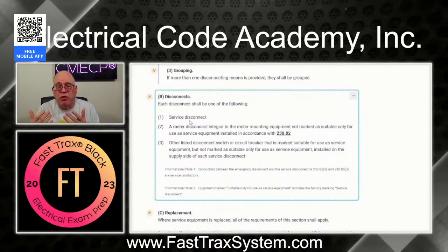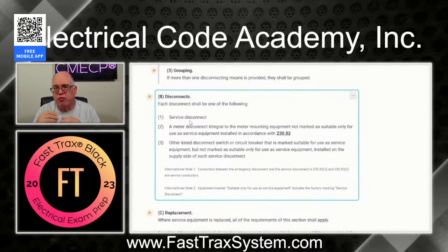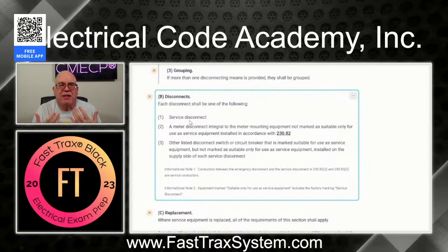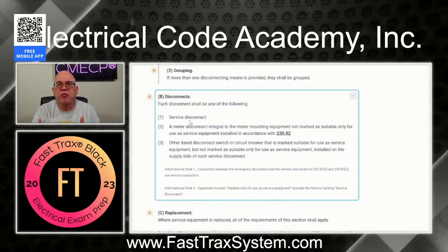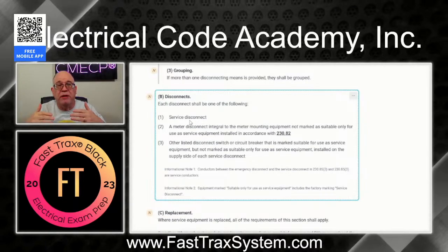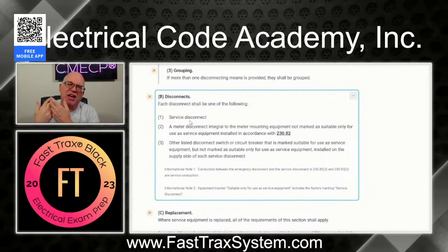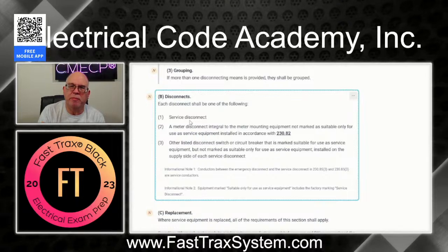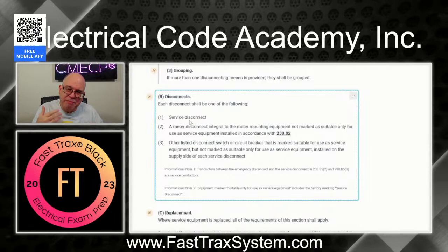We've talked about this: 312.5(C)(1), you can't take all the non-metallic sheathed cables through one knockout. That's not compliant. And if you were to try to punch holes in it, you can't take all of those NM cables out of the building, and then that small 1/4 inch gap is going to put you in a wet location, so you can't install NM cable there. So it makes it more complicated to do this compliantly, whether somebody allows something or not.